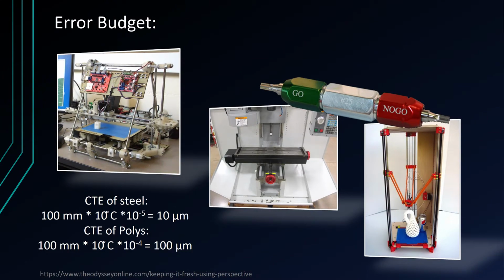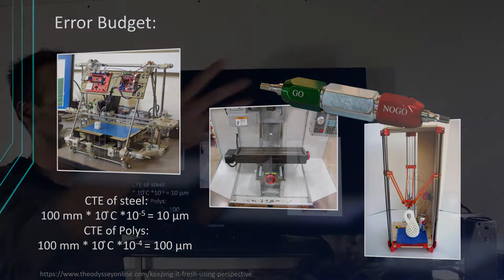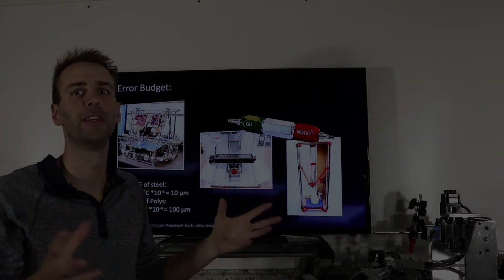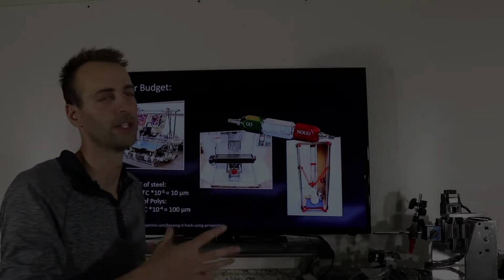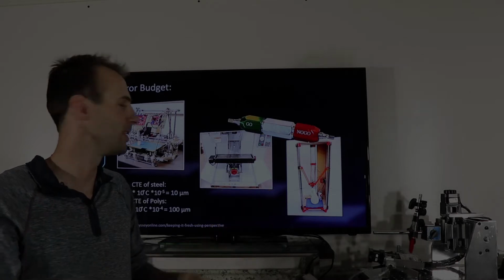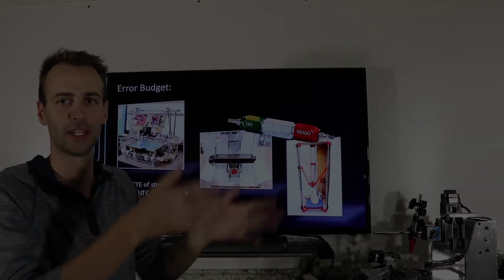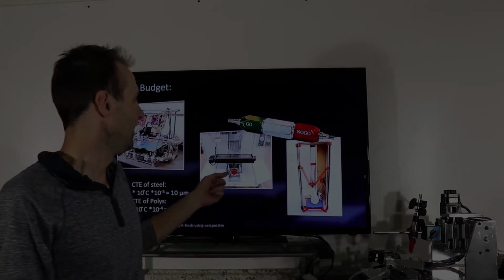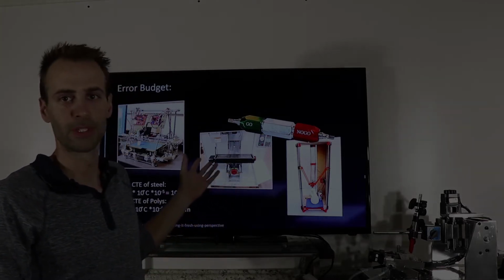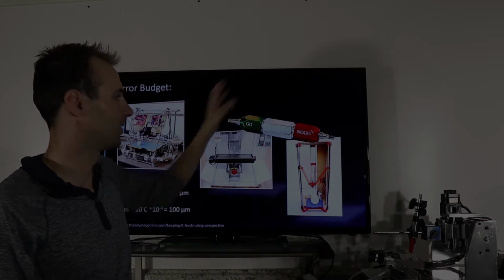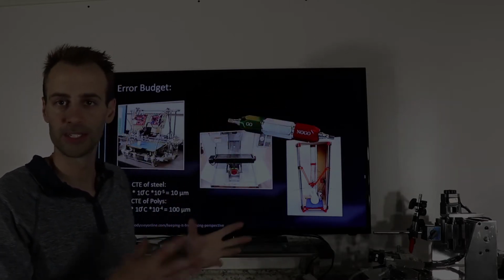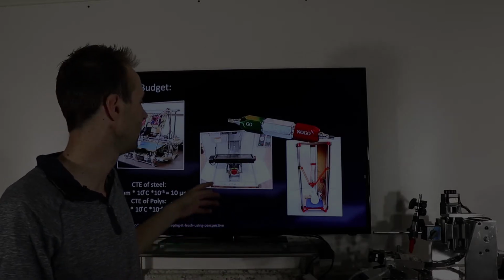First of all, when they cast these bases, they cast them and then leave them outside for a full year for all that stress to resolve, and it sort of weathers. Then they come in and start machining it to set the rails and build the machine. That's pretty crazy, right? And look at it, it's just super simple. All the controls are somewhere on the back of the machine, probably not anywhere near the frame. They're isolated, there's cooling fans, okay?